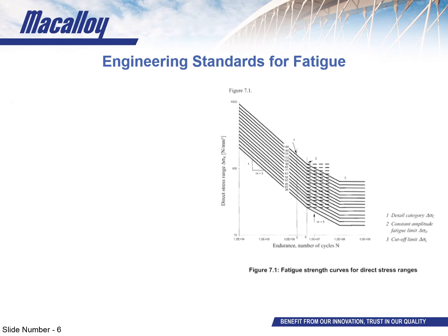Now there are two main standards to consider when it comes to fatigue and tension rods when you're looking at European standards. First of which is the already mentioned EN 1993 Part 1-9, which is the section that covers fatigue in general for structural steelwork. Of the two standards I'm going to talk about, this is the one that's more extensive for fatigue assessment when it comes to tension rods.